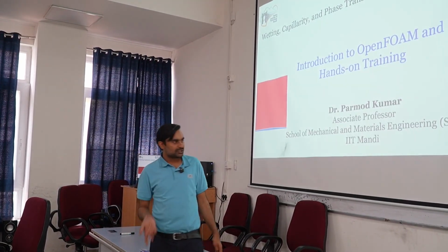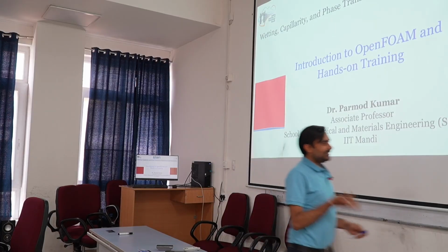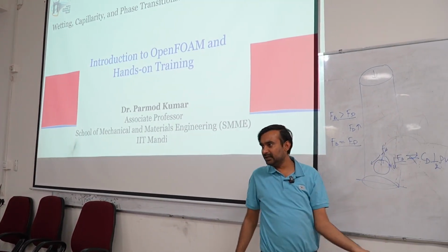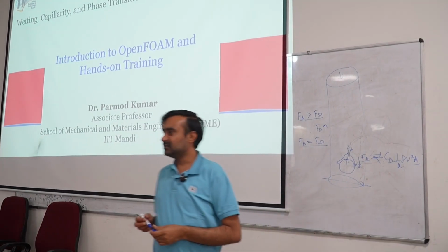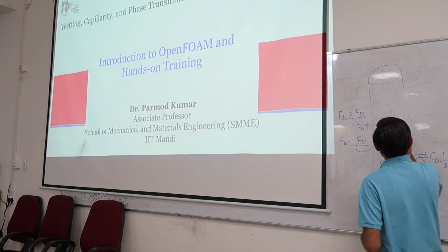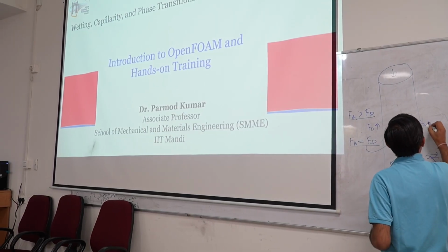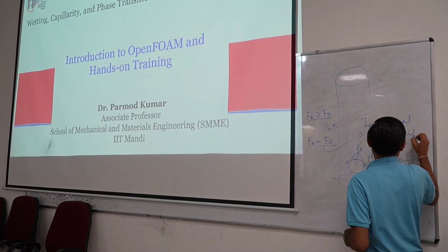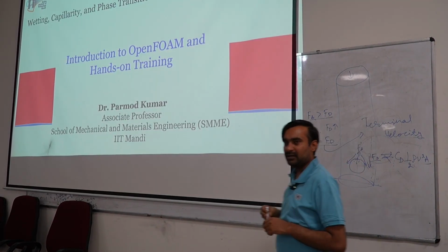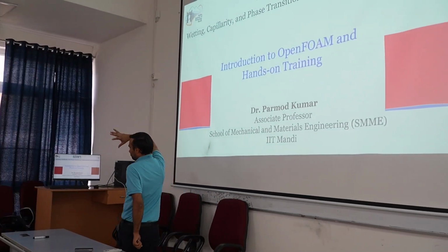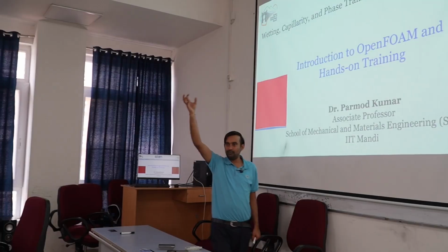If there is no further acceleration of the bubble, it means that with whatever velocity the bubble is moving, it will keep on continuing with the same velocity. That particular velocity in the balanced condition is what is called the terminal velocity of the bubble. Is this point clear?